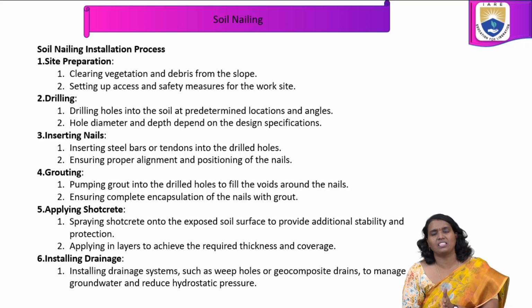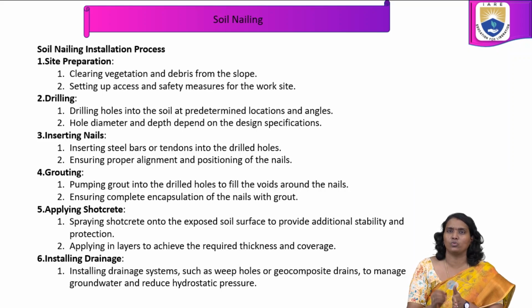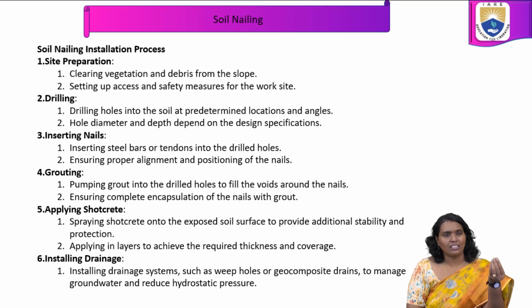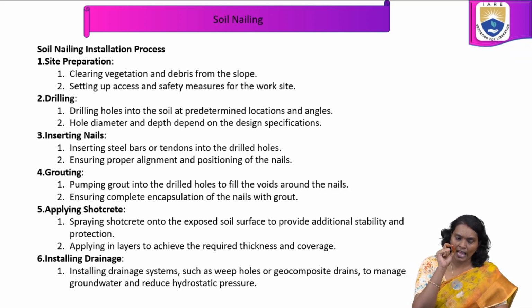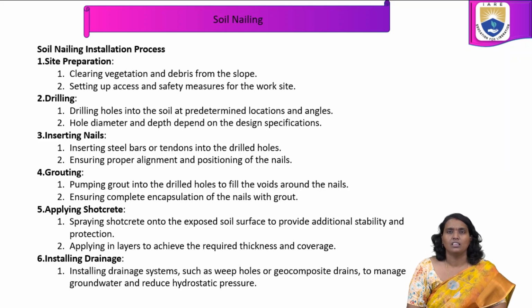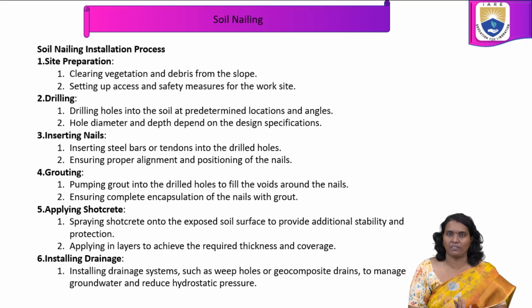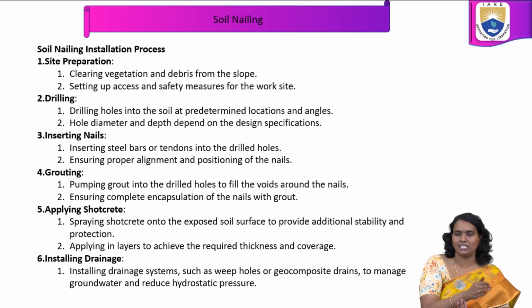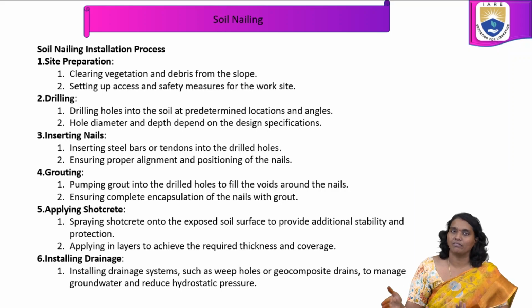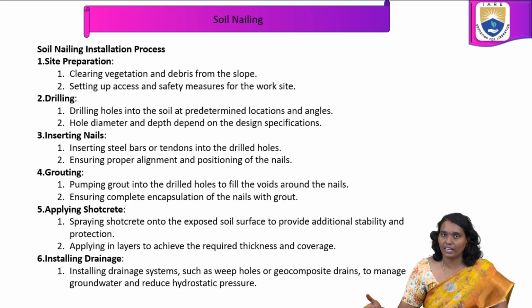The next procedure is drilling. Now we drill holes into the soil at the required depth. We already know the locations and angles, which we predetermine, and the hole diameter and depth depend upon the design specifications, designed specifically for that condition.